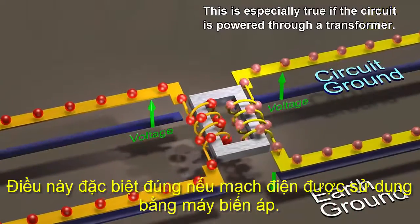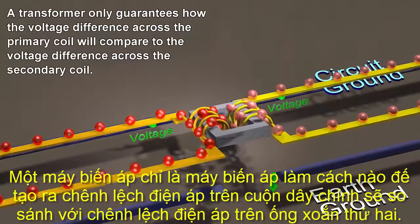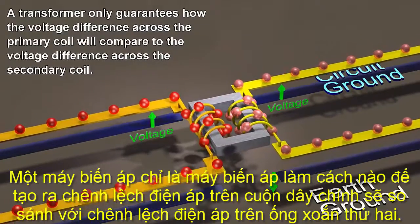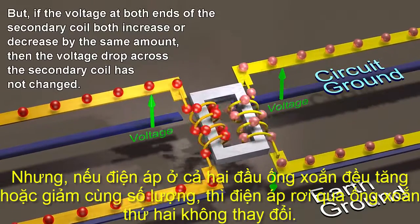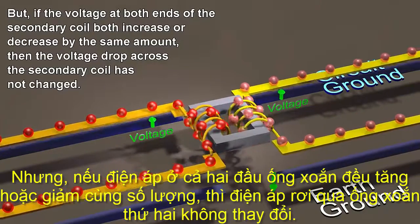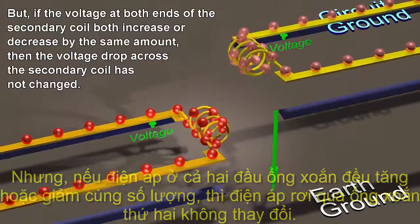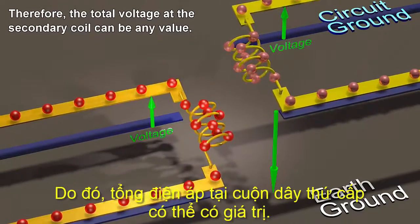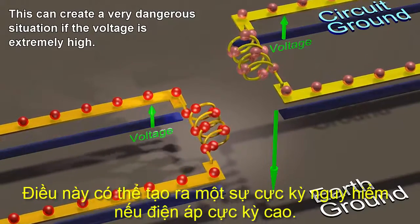This is especially true if the circuit is powered through a transformer. A transformer only guarantees how the voltage difference across the primary coil will compare to the voltage difference across the secondary coil. But if the voltage at both ends of the secondary coil both increase or decrease by the same amount, then the voltage drop across the secondary coil has not changed. Therefore, the total voltage at the secondary coil can be any value. This can create a very dangerous situation if the voltage is extremely high.